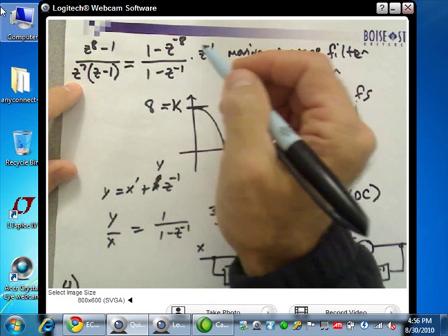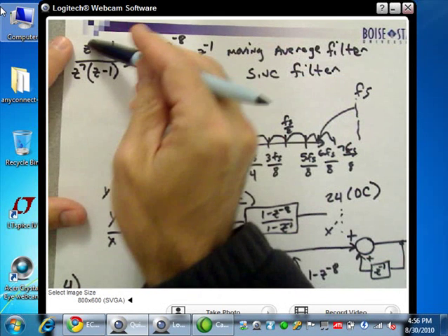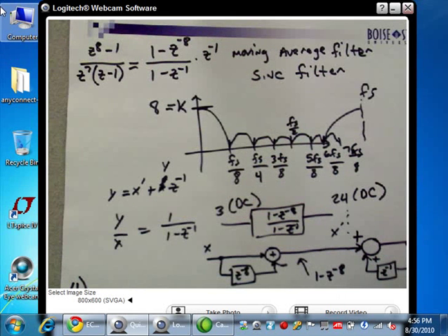Okay, so it's not trivial to see, but because of the way the poles and zeros interact, we don't have any delay. There's no poles at the origin. Do we all remember that? We only have zeros at the origin. And a delay would be a pole at the origin. Okay, any questions on this filter?